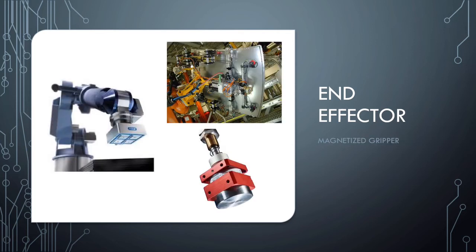We also have magnetized grippers. So you might think of maybe a junkyard automatically, kind of the big swinging crane that's pulling magnetic items out of a junkyard, for example. I know that commonly comes to mind. That's in a lot of movies and things. We see stuff like that. But these can also be used for a lot of different applications. So potentially any metal components where the surface finish is not super important. A magnetized gripper may provide a much stronger grip than a mechanical one, or if the surface is not perfectly smooth, it may provide a better grip than a suction cup.